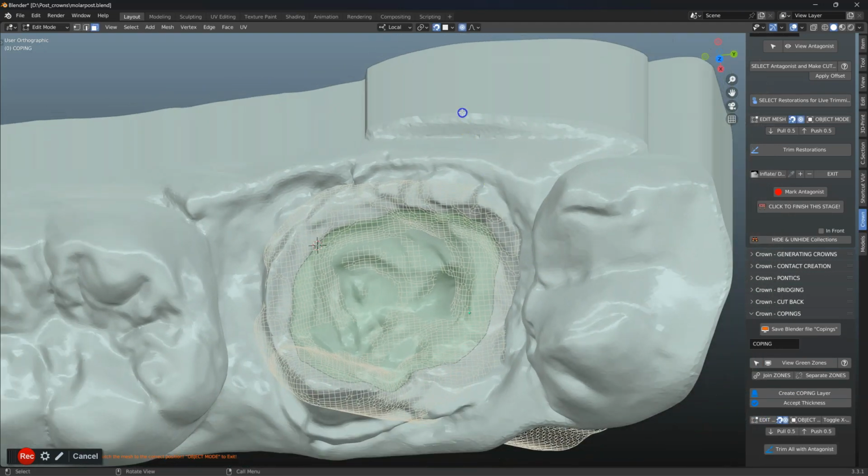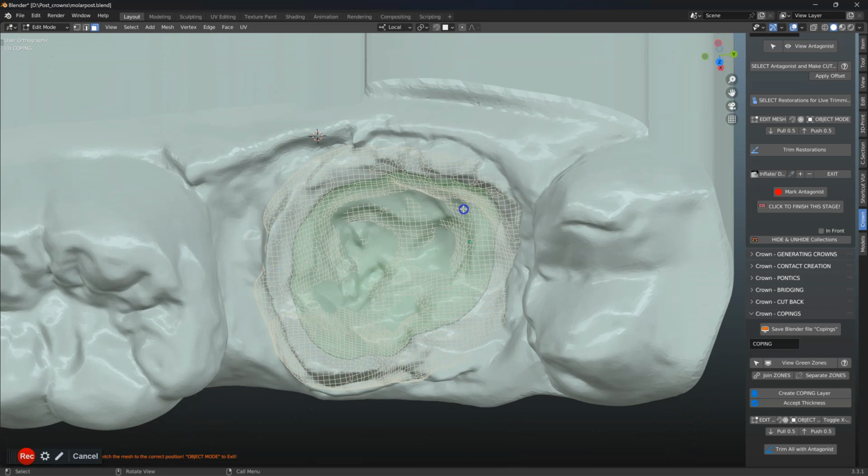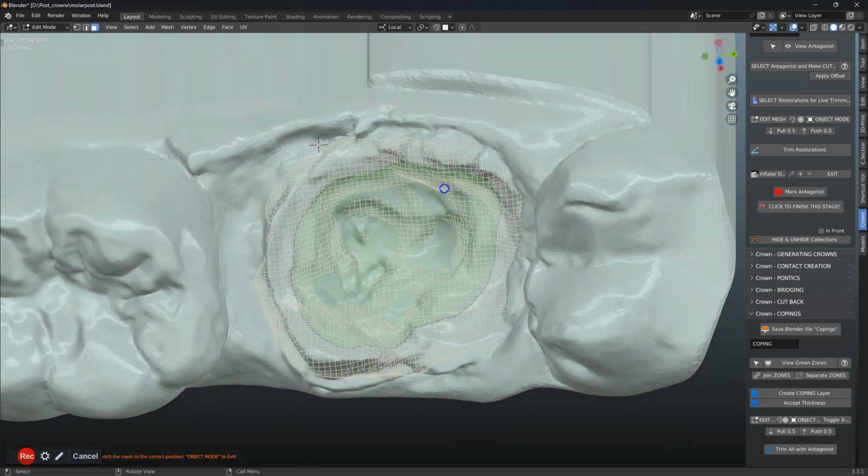Now here's the trick. I've got to make sure the magnet tool is off. The proportional editing tool is off as well. Then what we're going to do is use the C key and mark a whole lot of these vertices. At the moment they're all marked, so I'll click Alt A. It's a bit difficult to see with this theme. If you sort of know this theme, then it's okay, but if you don't, it's a bit tricky.